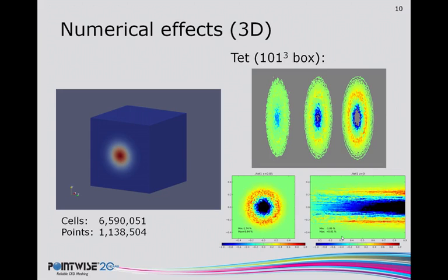Now, whenever we look at a tetrahedral grid, the picture changes dramatically. So despite having the same edge count on the outer boundaries of our cube, the tetrahedral cells, because of that 6:1 node ratio, actually produces a grid that has over 6 million cells. So this is a fairly large grid for such a simple test case. However, because of this non-zero skewness throughout the volume, we wind up introducing error that accumulates more and more as the solution is propagated throughout the volume. So you can see now we have appreciable error. The error starts off relatively small, it grows larger, and it grows larger still.